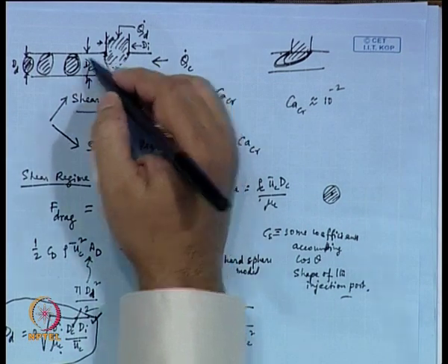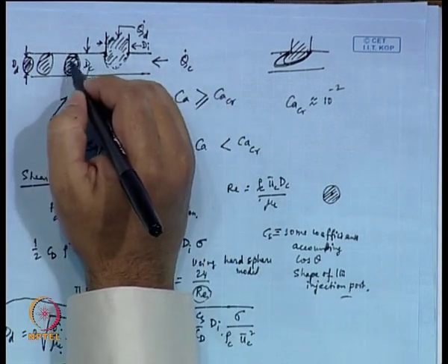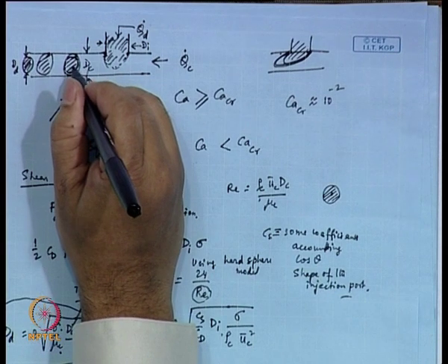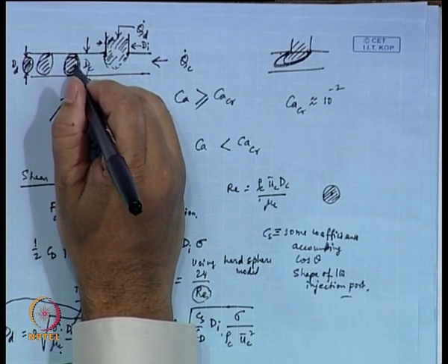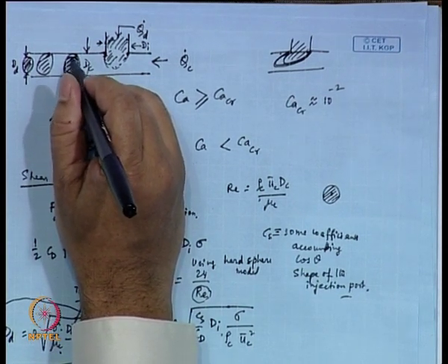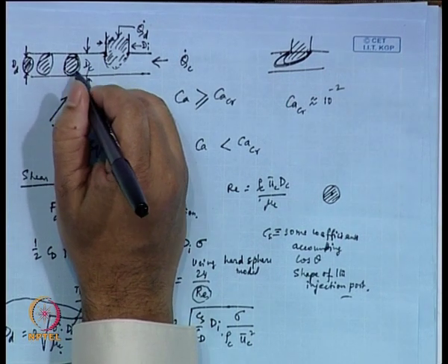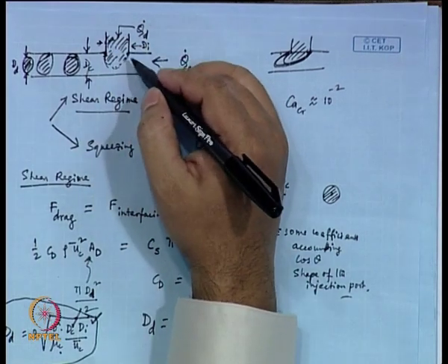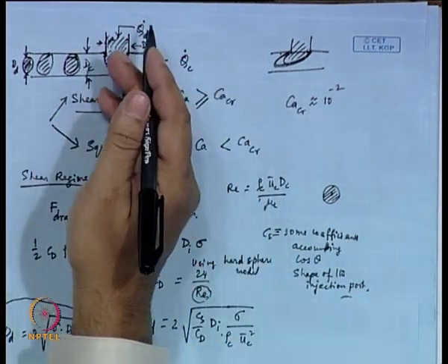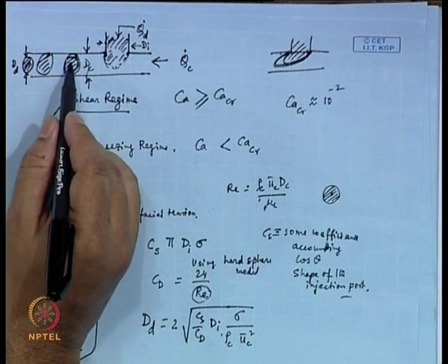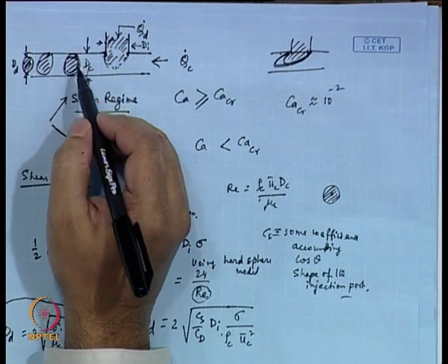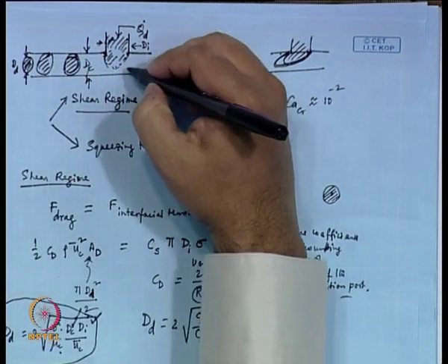After the droplet forms, there is a method called PIV, particle image velocimetry, where you can see the velocity vectors within the droplet, and you will find that there is a vortex inside the droplet, because you are producing a shear.